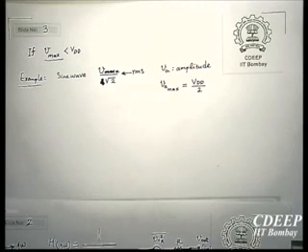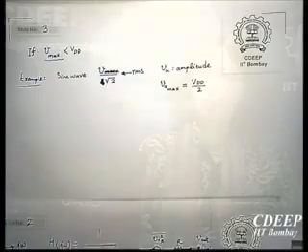Of course, there are cases like, for example, in a power amplifier, where you are able to generate voltages above VDD, where we use inductors. Right now I don't consider that, but even in that case, you have a limitation on the maximum voltage the circuit can operate with, because there are other issues like power dissipation, thermal budget, stress on the device, and other breakdown issues.